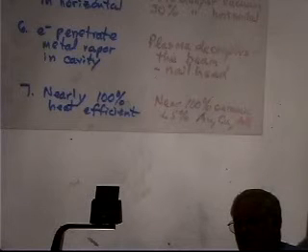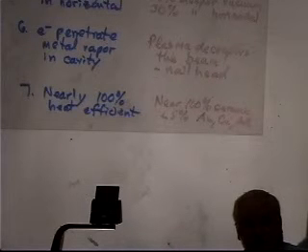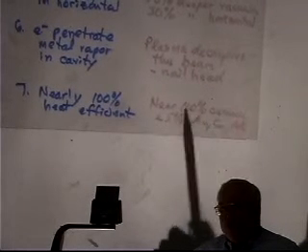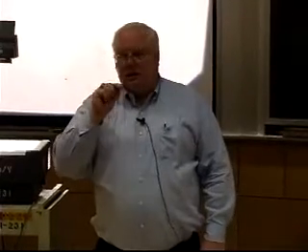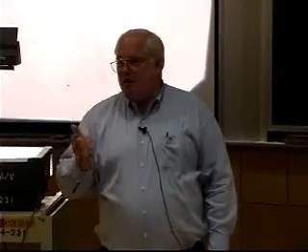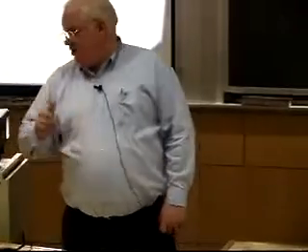Anybody have an idea why you might gold plate the surface after you made this copper mirror? It has to do with the fact that copper will tarnish and gold will not. If the copper tarnishes, I have copper oxide. The heating of a ceramic like copper oxide is nearly 100%. So if I get some tarnishing and then hit that copper mirror with a high power laser, I will heat up those oxides and thermally pit the surface of my mirror. I'll destroy my mirror because it oxidized. Whereas if I have gold on the surface, gold doesn't oxidize and maintains its good reflectivity, and I only absorb 5% of the heat, which I hopefully carry away through the copper.